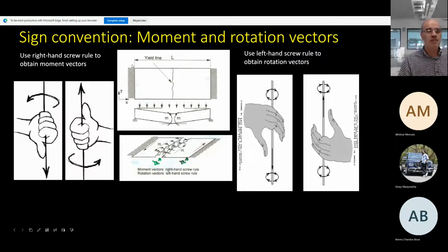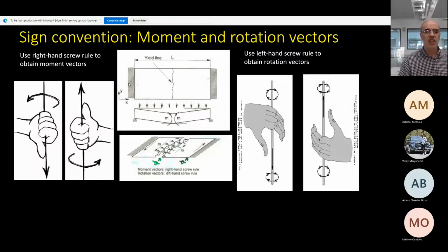Okay, just focus with me on this slab here. We have a rectangular slab, which is simply supported on these two edges here. So if I take a cut there, if I take a strip, this is what you see. This is your slab with the UDL. The slab is loaded with the UDL, which could be self-weight or whatever. And do you agree with me that these are the direction of the moments? Same as we did before with the plastic theory. It's exactly the same. Okay, so we have got moments here.